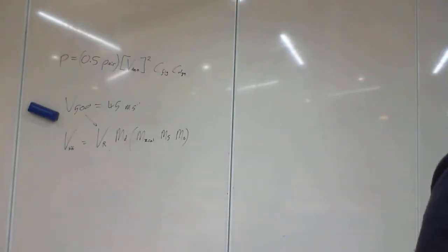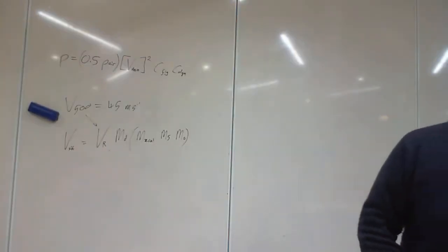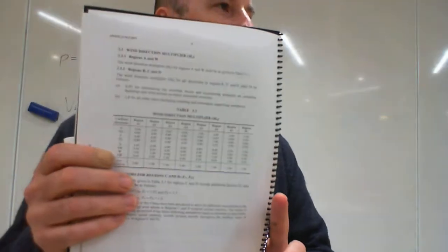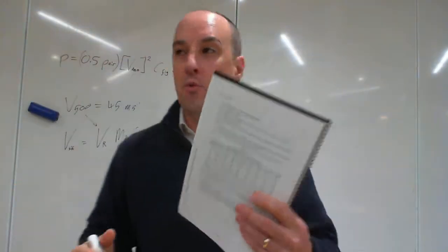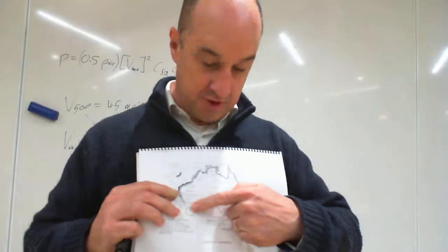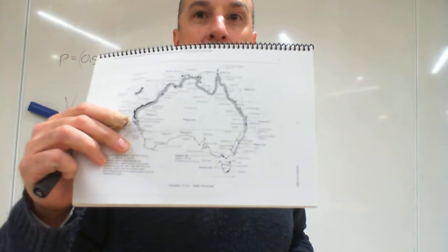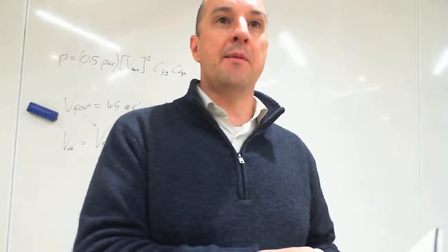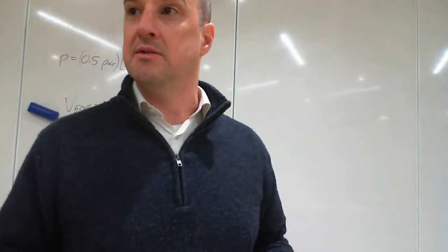Okay? So in region A1, those factors go from 0.8 to 1.0. And in the westerly direction, it's 1.0. So that's saying in region A1, which is all that region there in Australia, the wind blows hardest from the west. And from other directions, from the north, for example, it's only 80% as fast as from the west.